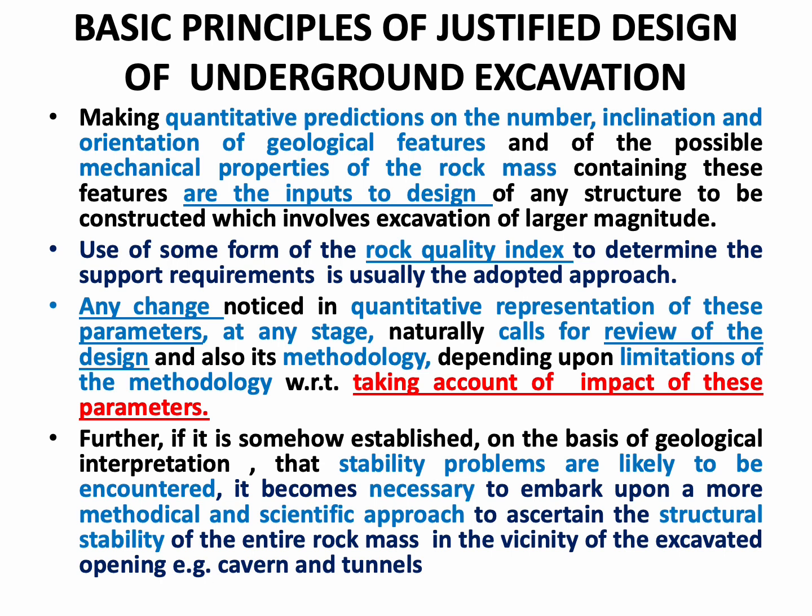This is very important: at any stage during the excavation of large caverns, many geological features will be exposed, and based on those geological or site conditions, if it is justifiably seen that stability problems are likely to be encountered, then it becomes necessary to embark upon more methodical and scientific approaches, rather than just relying on the rock quality index, to ascertain the structural stability of the entire rock mass in the vicinity of the excavated opening.